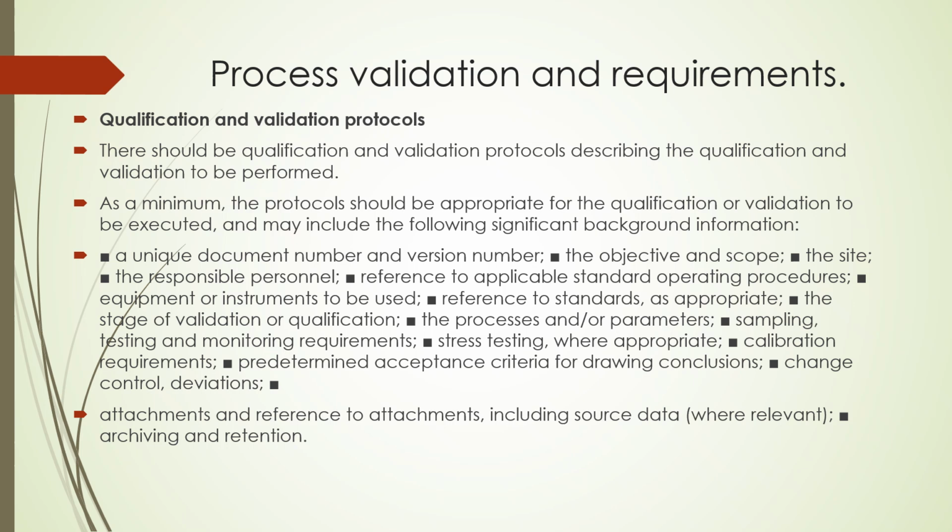The site should be mentioned, the responsible personnel, a reference to applicable standard operating procedures, equipment or instruments to be used should be recorded, a reference to the standard as appropriate should be recorded, the stage of validation and qualification to be mentioned, the process and parameters should be mentioned, sampling, testing, and monitoring requirements should be mentioned, stress testing where appropriate should be recorded, calibration requirements should be mentioned, predetermined acceptance criteria for drawing conclusions, change control, deviations, if any, during the qualification or validation should be recorded in the report.